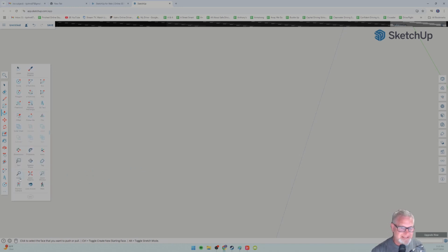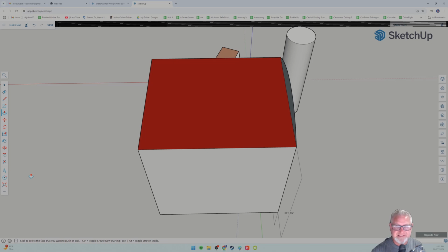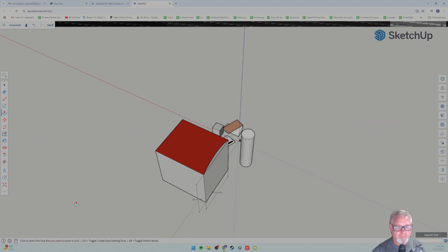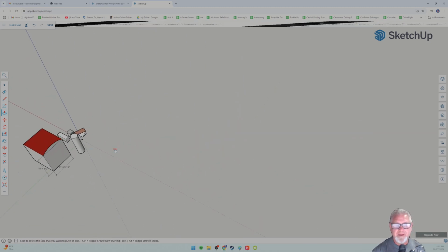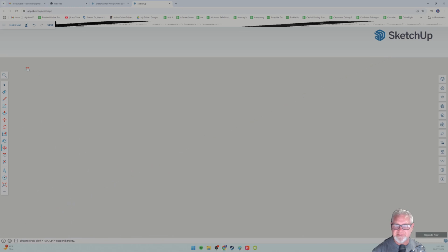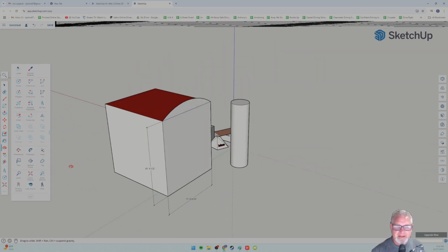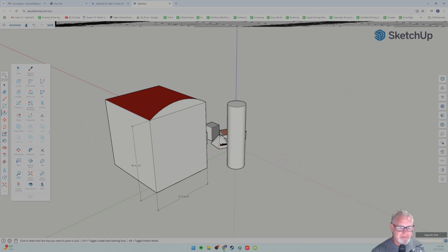If you go find that Zoom Extents tool, it will zoom back in as close as it can to everything you've designed. So that's kind of, I call it the Find My Stuff tool, because sometimes I do that and I'm like, where am I? Where is it? Like, I'm not really sure. And you can't even find those lines because you're so far away. I mean, 3D designing sometimes gets really confusing, and you kind of feel lost sometimes. So sometimes you want to just recenter and just click on that Zoom Extents and zoom yourself back in, which is great.